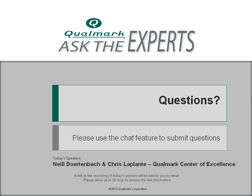Okay, thank you. And I did have a question that came in actually during the HALT portion of this. What about thermocouple placement? Did you want to talk about any differences between HALT and HASS? And then what about triaxis placement? Well, in HASS, you won't be monitoring the product at all thermally. There's no point in taping thermocouples on. It's the HASS during validation, fixture validation and screen validation. You'll have lots of thermocouples in there making sure everything's behaving the way you want it to.